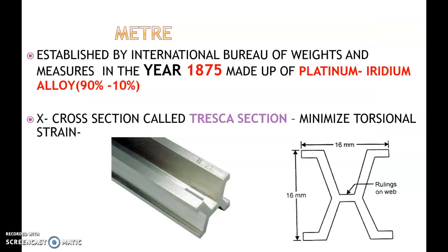For the meter standard, instead of a bronze bar, an X cross section called the Tresca section was used to minimize the torsional strain, because this is lengthier compared to the yard standard. And this Tresca section is made of platinum iridium alloy, with 90% platinum and 10% iridium.